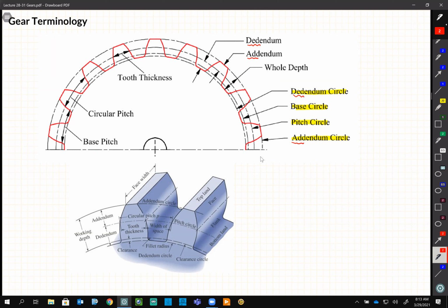And when we talk about the depth of a gear, this is the difference between the inner and outer edge. Okay, so the tooth thickness is what you can see on this image, again, from one side of a tooth to the other side on the pitch circle. And do not confuse it with the width. The width of the circle in the picture at the bottom is what goes inside the screen, like on the picture at the top. So we have the width and we have the thickness.